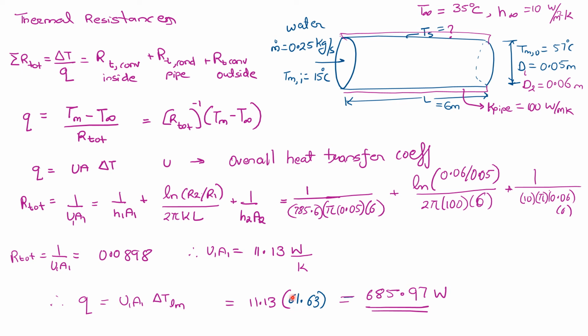I've taken the logarithmic mean temperature that we calculated in the previous method 2 and calculated the heat transfer rate, which is wrong because in method 2, in the definition of the logarithmic mean temperature, we had considered surface temperatures instead of T infinity.